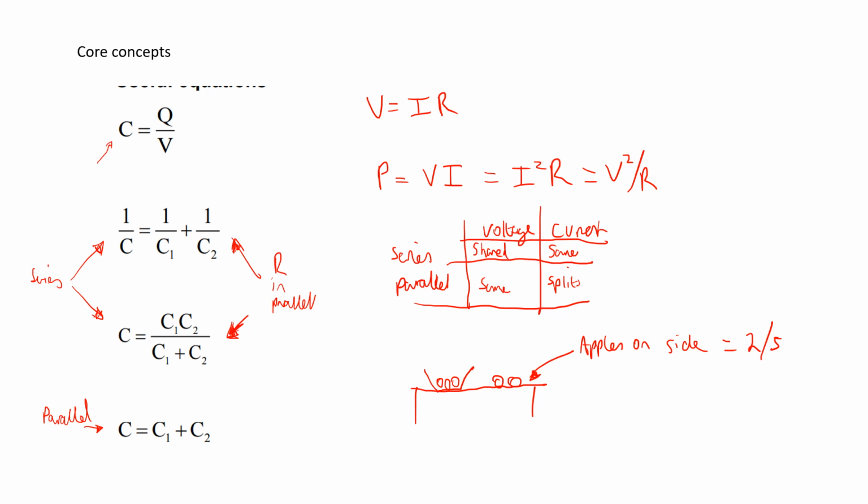That's ratios. A lot of this paper is on ratios, yeah? So you can see the same thing with this. If you've got something like 10 volts, 0 volts, 2K and 3K, V equals 2/5 of 10 volts, which would be 4 volts.